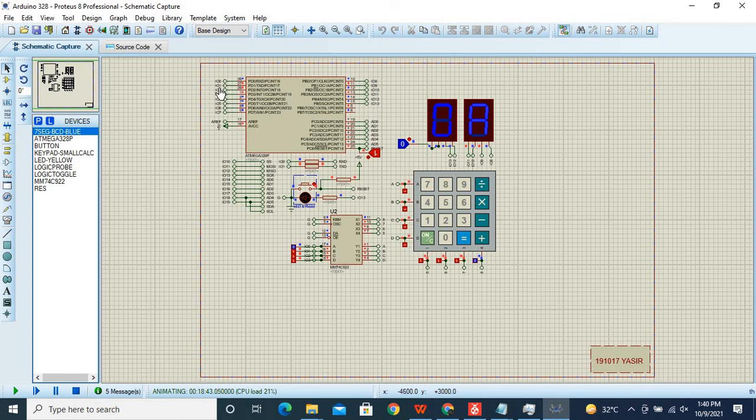And here we have got our inputs right here. So this being the least significant bit, and this being the most significant bit, and this being the least significant bit for the input, and this being the most significant bit for the input. And we get our input right here, and we reflect it right here. These two were out of range because 9 plus 9 equals 18, and it was never going to use these two anyways, so I just gave them a logic 0, which means a ground in practical.